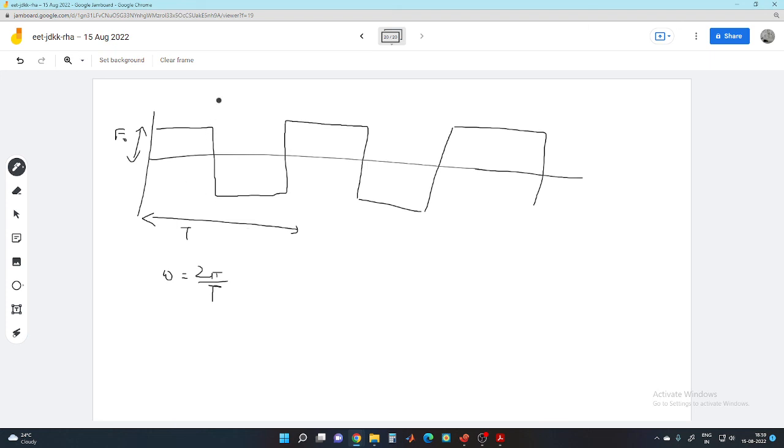And this ratio is actually equal. This is T by 2, this is T by 2. There are cases where this is actually called the duty cycle. This length to the total length is called duty cycle. This equal refers to 50% duty cycle. So we are assuming that it always remains 50%. There are cases where it changes from 0 to 100. 100 is basically a step function, and we are assuming it is a 50% duty cycle. So I just want you to explore what will happen in this case.